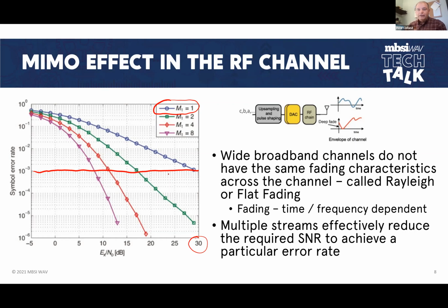If you connected the CPE up to a base station, for example, near the bottom edge of performance, let's say you've got a 20 megahertz channel and you connect it up at negative 85, and you're going to flow 50 megabits or something across this channel. Everything works good when you first start off, and then a little while later, because of the fading that goes on, the customer starts to complain because there are times where they have outages. There are times where they can't decode that data, all sorts of trouble.